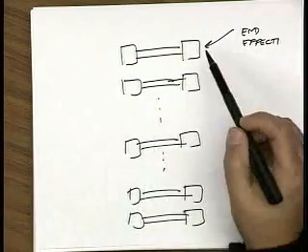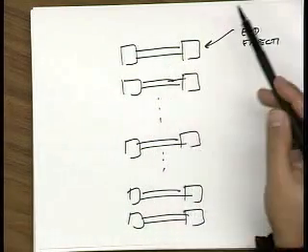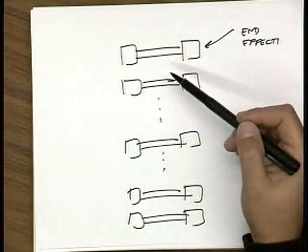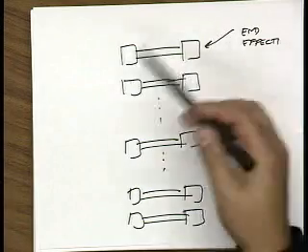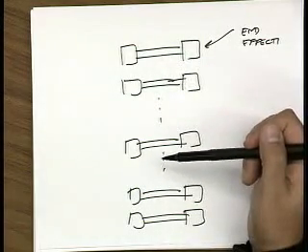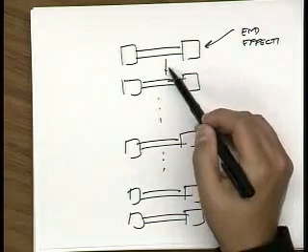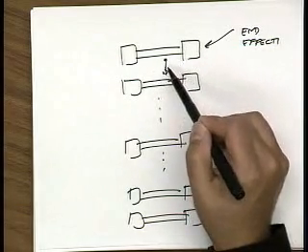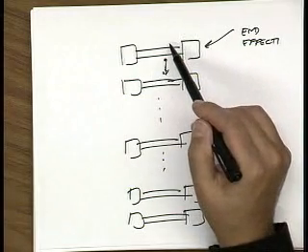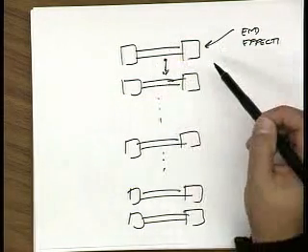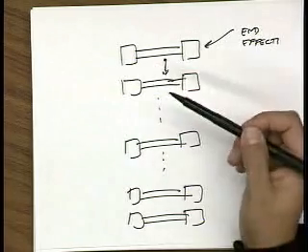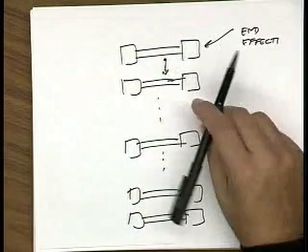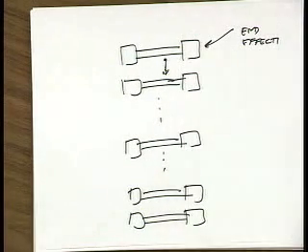In fact, what you're going to find is that in fabrication, the guy on the end is actually going to look different because of the way you actually etch these guys. There's etch effects. The space between these may be quite small, and the amount of etchant that gets into these spaces is going to be different than the amount of etchant that gets on the outside. So you're going to get a systematic error. So what you want to do is protect yourself. Just put dummies at the end and don't use the dummies. That's it. Very simple. Okay? Questions?